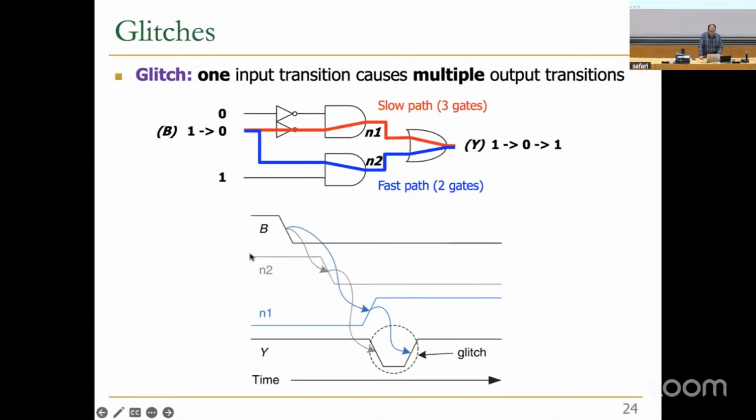So here is basically the diagram that I already discussed, showing why it's happening like that. And the output, for a very short amount of time, can go to 0 and then come back up to high voltage. And that time is TPD minus TCD? Right, at most. Yeah, around that, yes.